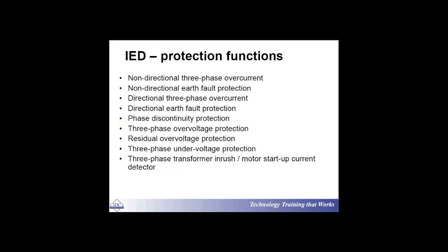So if that IED that you have got is mainly a protection device, well, it can provide you with directional or non-directional protection against what? Against three-phase phase-to-phase faults, for which its overcurrent element will work, or single phase-to-earth faults, for which its earth fault element will operate.